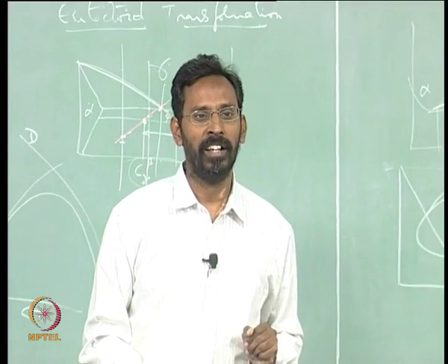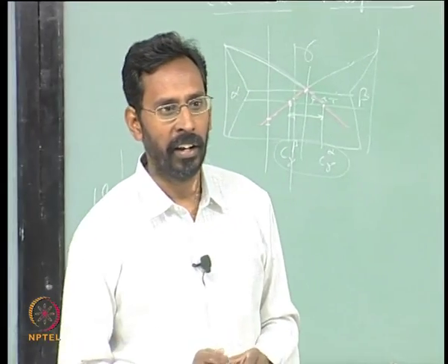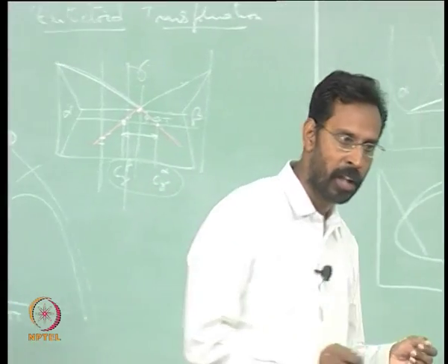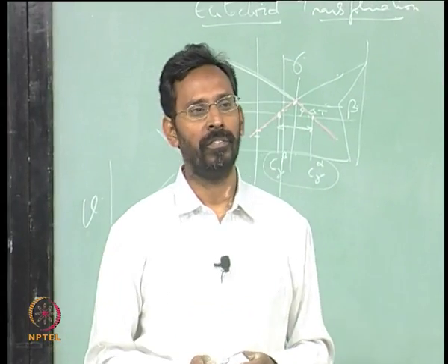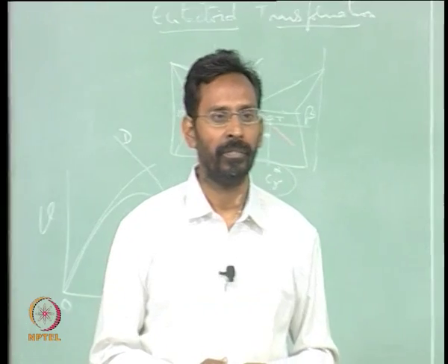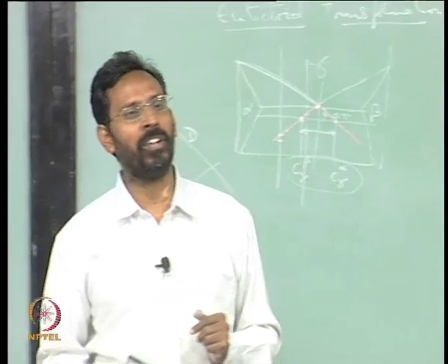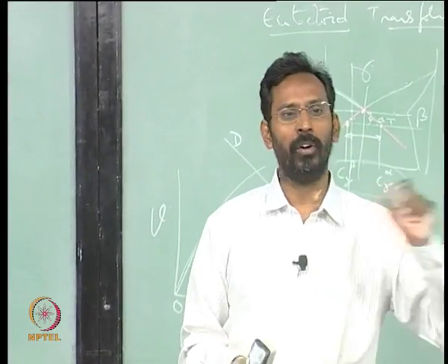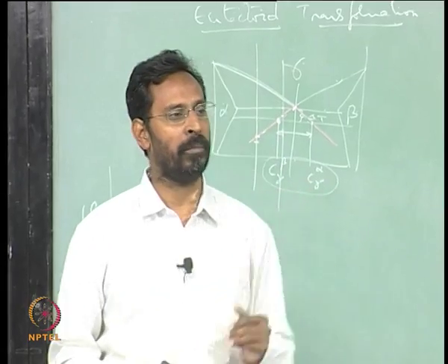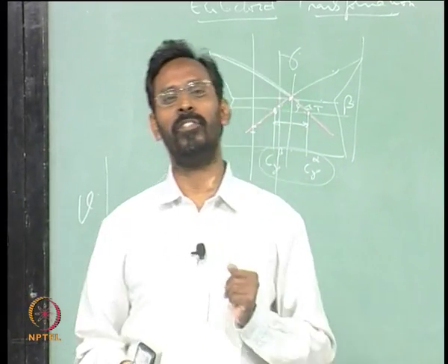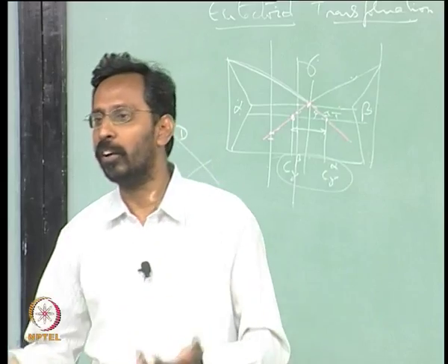In principle, the lever rule tells me how much ferrite there is in 0.6% carbon steel. It is 25%, it is 1/4, 3/4, because 0.6 by 0.8, that is what it is. So it is about 75% of eutectoid mixture and 25% of ferrite, and if I now take the same 0.6% carbon steel and do normalizing, you will not see 25% of ferrite, you may see 15%, you may see 20%, depending on the cooling rate that you have adopted.